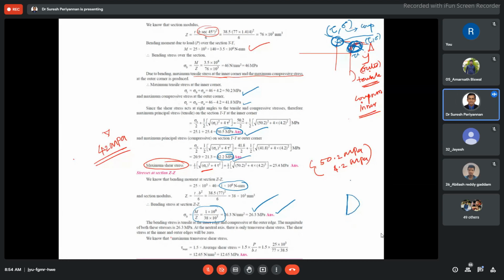But we discussed the shearing stresses. This is the middle layer, and these are the outer layers. In bending stress, it is maximum at the outer edges, and the middle layer is the neutral layer, 0. The maximum is tensile on one side and compressive on the other. This is the bending stress, sigma B. This is tau, the shearing stress: maximum at the middle, and both edges are 0.